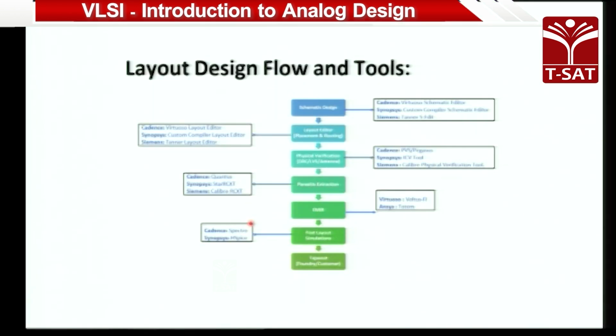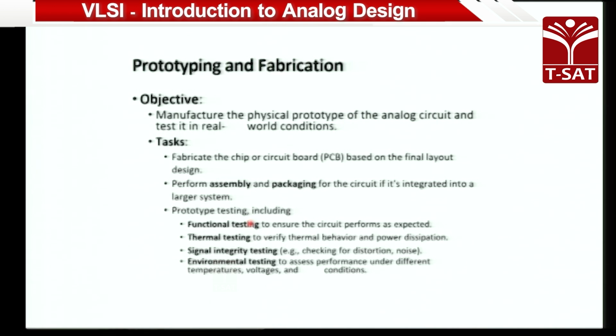For the sake of time, I am not going through it in detail, but I mentioned some part of it during this discussion. Prototyping and fabrication is another component. Once we are done with layout and post layout simulations, we plan for prototyping: when the design comes back from silicon fabrication, how we test it, how we interface with that design in real time and get the outcome. We plan for prototyping and fabrication, validation and debugging, finalization and production, right.